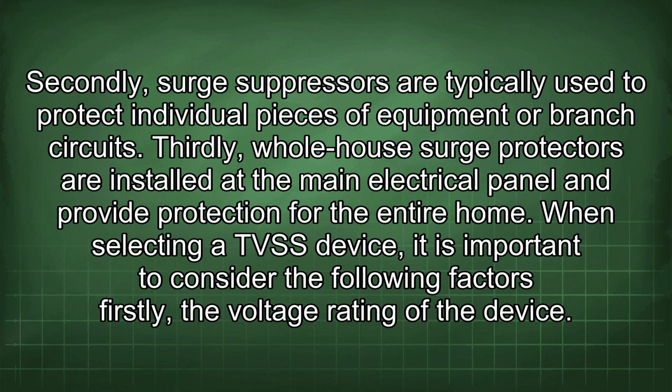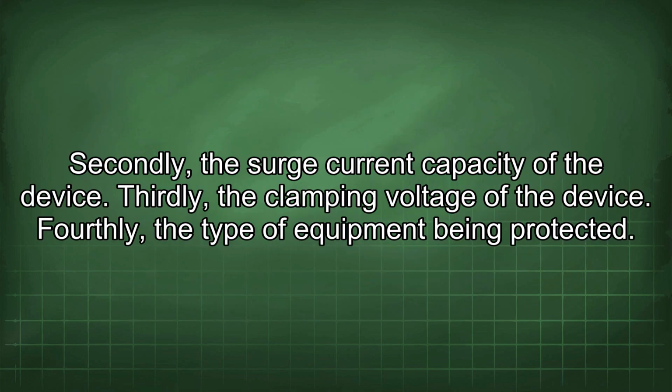When selecting a TVSS device, it is important to consider the following factors. Firstly, the voltage rating of the device. Secondly, the surge current capacity of the device. Thirdly, the clamping voltage of the device. Fourthly, the type of equipment being protected.